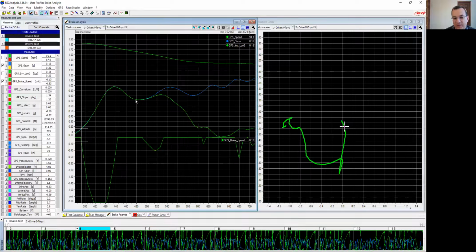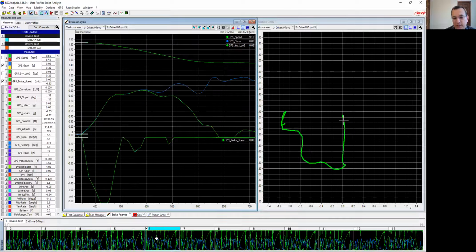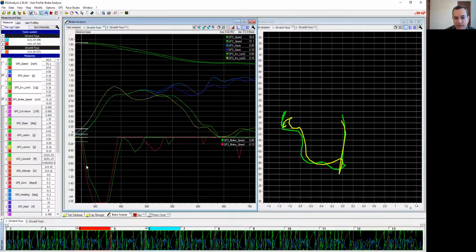Right? We don't have that same dip, but maybe this is telling us that our problem is on this side. The transition was good, but maybe we could have waited a little longer and built that braking G a little bit more quickly. And let's turn on, yeah, you can see that here in the brake aggression, right? The brake aggression is a little bit off the scale here, but the green is a much softer brake aggression than it is here in the red.